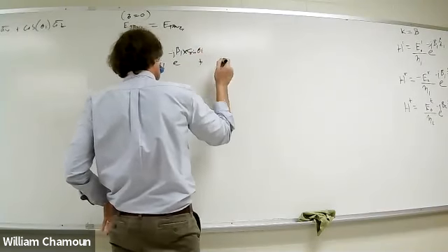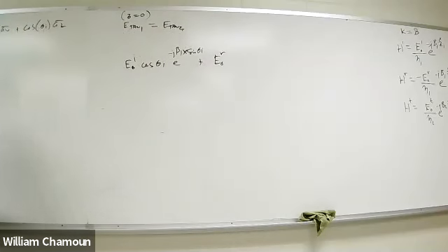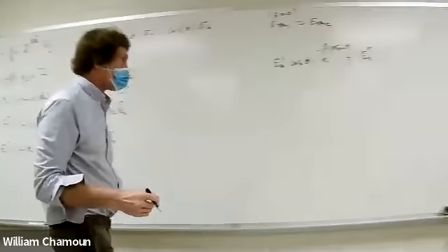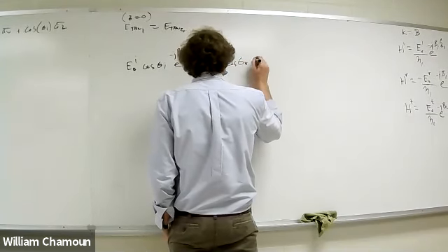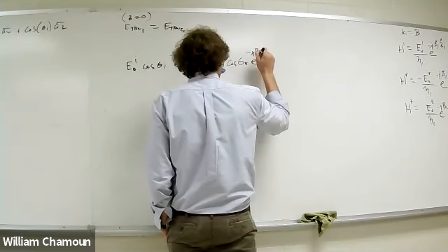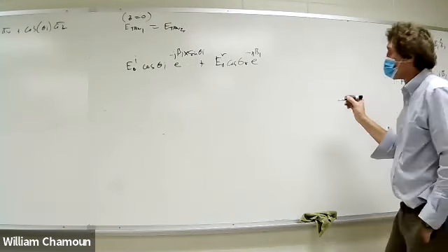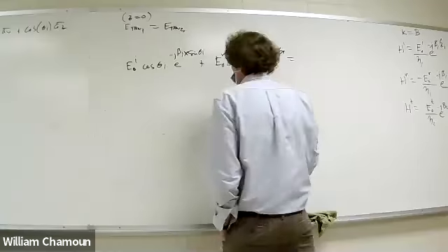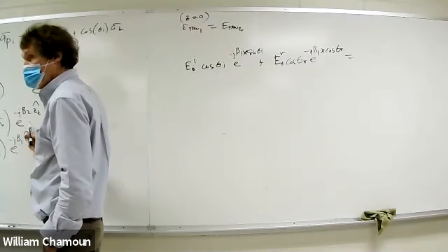It's that plus the reflected wave, right? I have E naught reflected, times cosine of theta reflected, times E to the minus J beta 1. Now I need Z reflected, but I let Z be 0, so it's just X sine of theta reflected. And that has to be equal to the transmitted E field's tangent component everywhere on that boundary for any X.